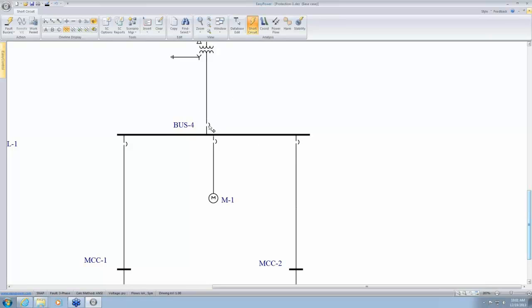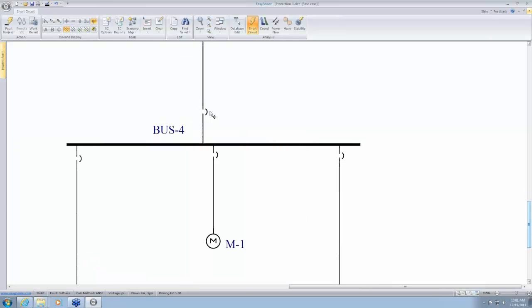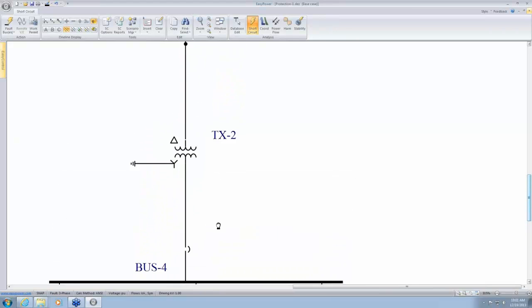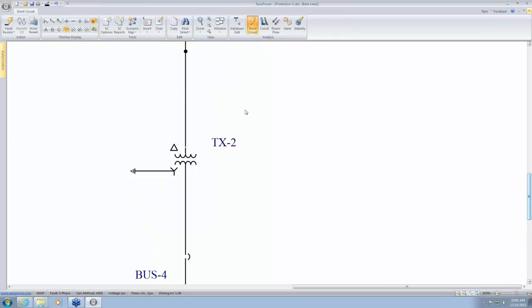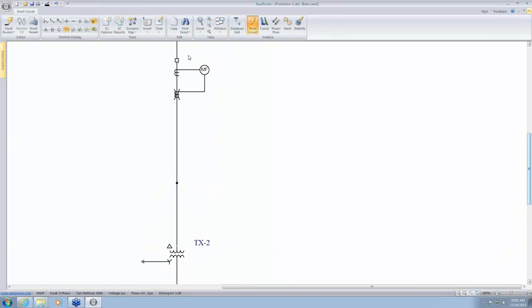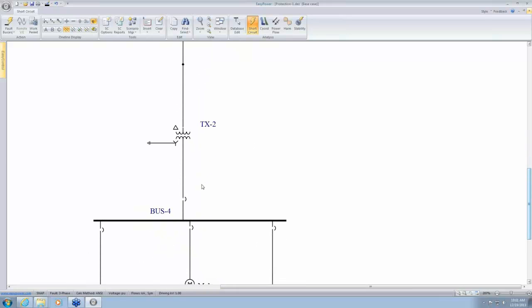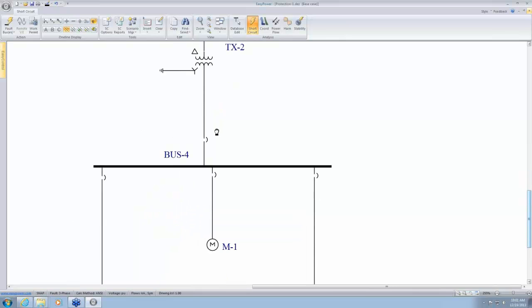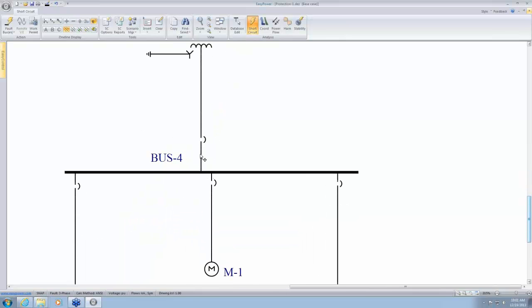equipment. For example, if you have this main breaker, if you get an arc on the line side of the main breaker, then you would have to rely on an upstream trip device. In this case, it's going to be this relay upstream to the switchgear that will need to trip and protect the worker. If you have an arc flash on the load side of the circuit breaker or on this main bus, then this main breaker tripping is going to interrupt the fault.